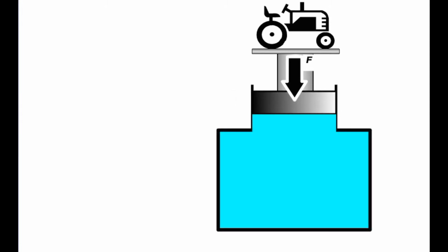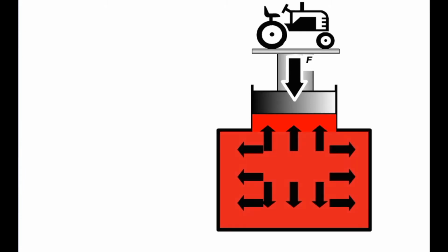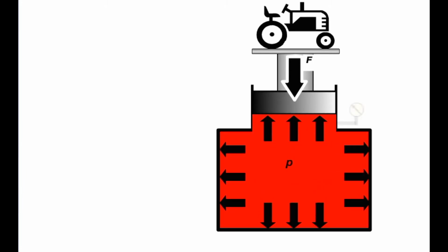The way in which liquids and solid bodies transmit force is different. In this example you can see a load arranged on a fixed mounting. The mounting transmits the weight in one direction only, downwards. If we place the load on the movable lid of a container filled with liquid, the weight is acting on the liquid and pressure is generated within it. However, the pressure generated not only acts directly downwards, but is spread equally throughout the liquid in all directions. The pressure always acts perpendicular to the walls of the container.